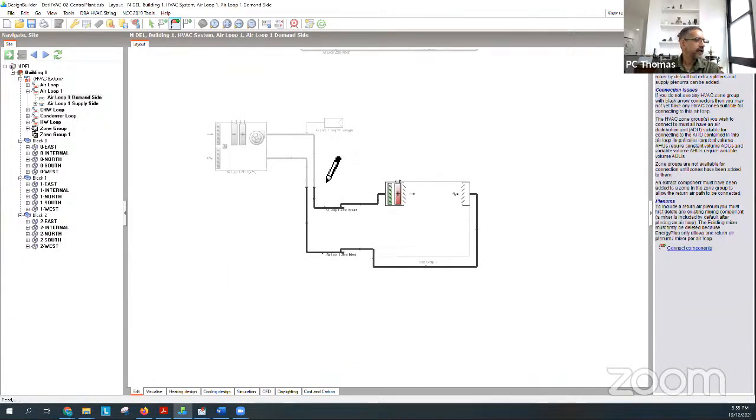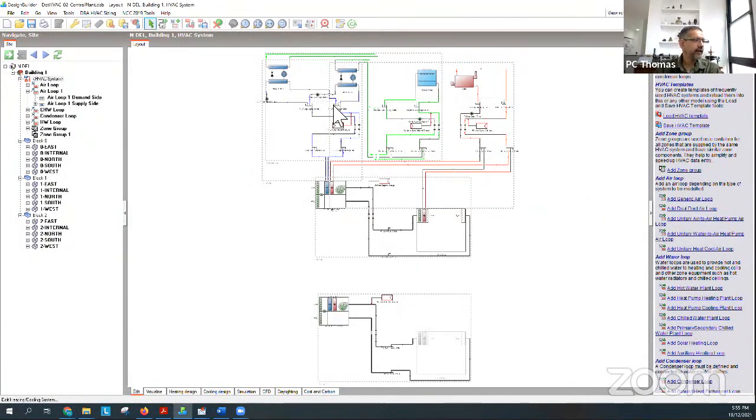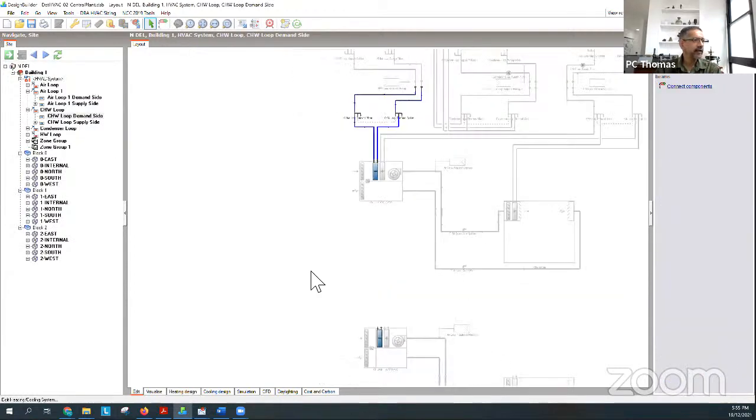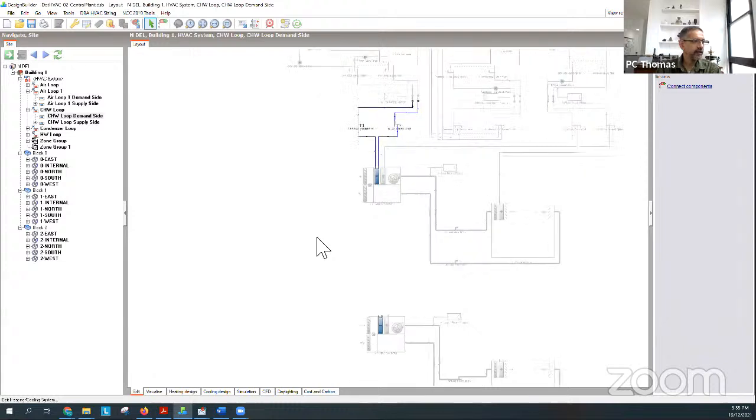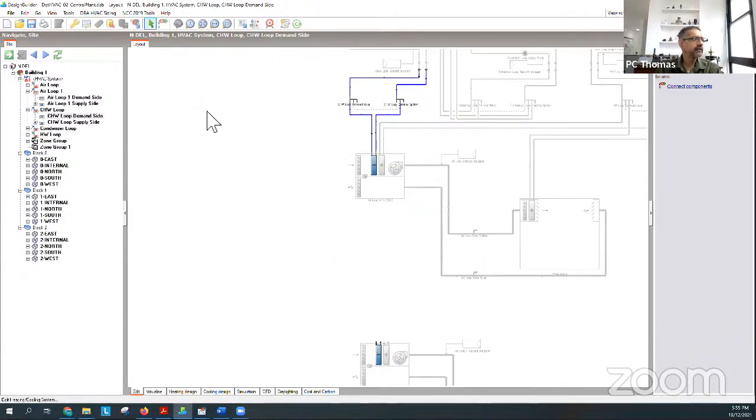And then I need to hook all these coils up in the right places. So for the chill water system I need to connect the coil. For the hot water system I need to connect these 4 coils. Okay, so let me do that. I'll go to the chill water system, go to the demand side, and you can see here it's telling me that these can be connected.